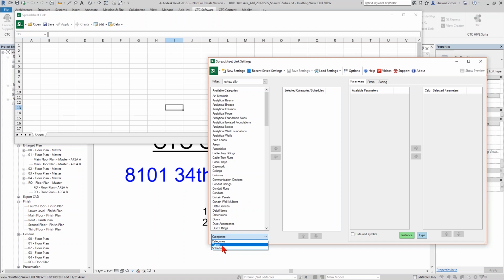There's a types option. Those of you who are BIM managers, this is a great way to go through and do some basic type manipulation, including things like renaming types to follow some kind of naming convention. You can use this to help automate that process. So this will give you just the types, no instance properties, just type definitions.